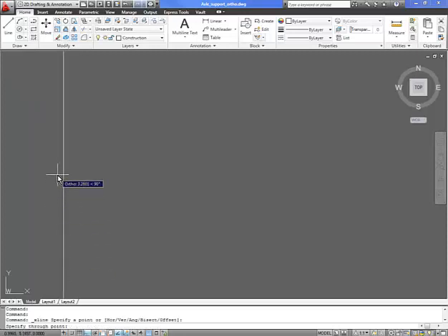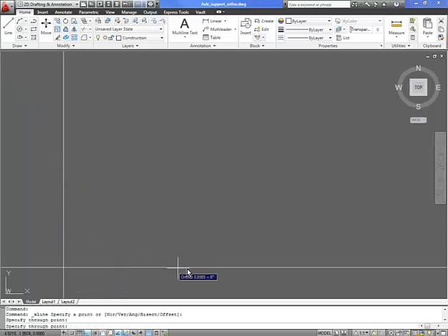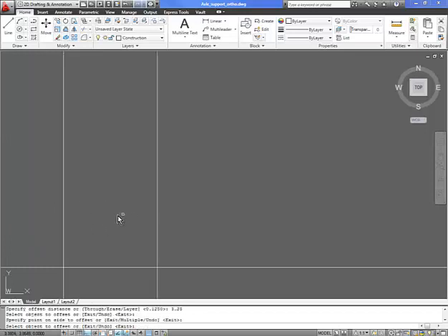We're going to draw a vertical line, and then we're going to draw a horizontal line. What we're doing is establishing our bounding rectangles for this project. We're going to use the offset tool. The width of this one is 3.25, so we need to offset this one over 3.25. The height of it will be 3.125. That will be the height of the front view. Front view is right here.